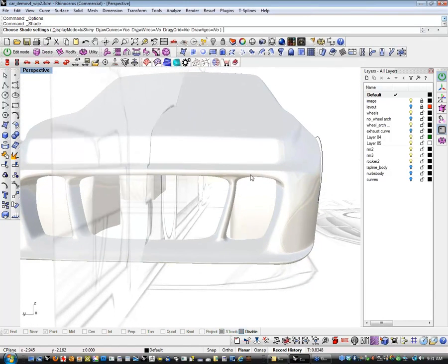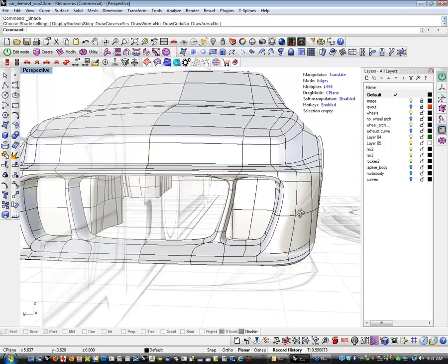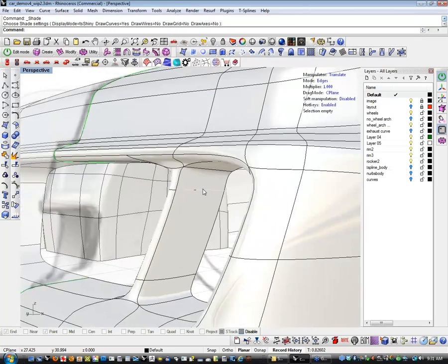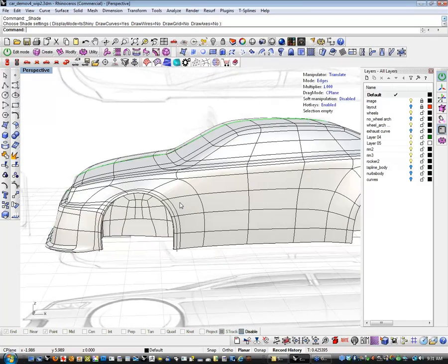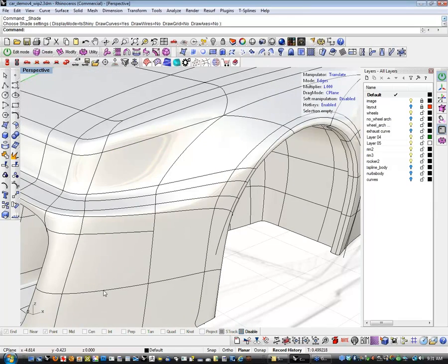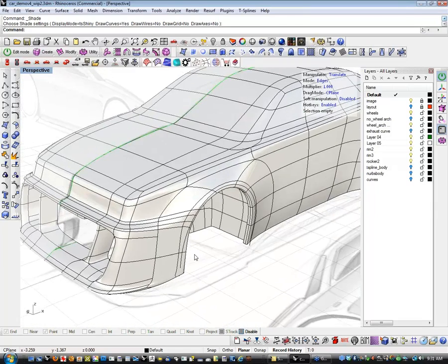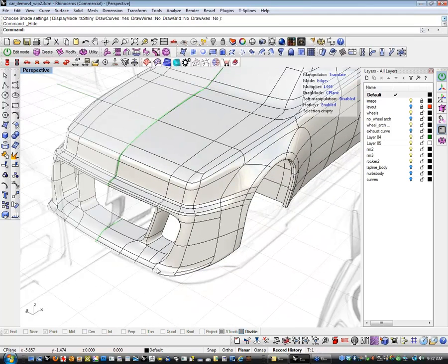And you have to get out of your NURBS head a little bit when you're doing T-Splines modeling, because a lot of the NURBS rules don't necessarily apply. You're absolutely right. If you were doing something like this in a NURBS model, that would not necessarily be what you want. I've got a curve here. Let me hide that. But in a T-Splines model, that's exactly what you want, because you want the detail where you want detail, and you want big, wide patches where you don't want detail.